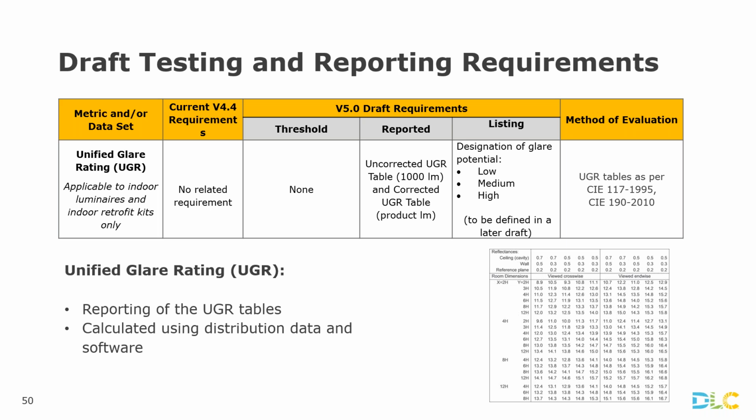And the UGR table refers to a set of values of the luminaire tested based on a preset room definition. Therefore, it is an estimation. However, it is useful and gives additional information on the likelihood of glare that a product, like a luminaire, can produce.